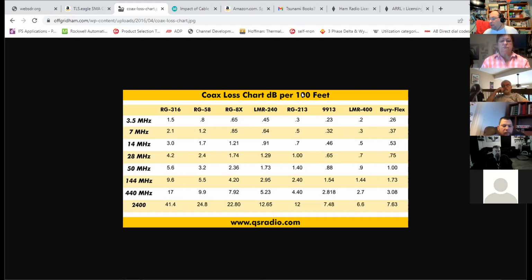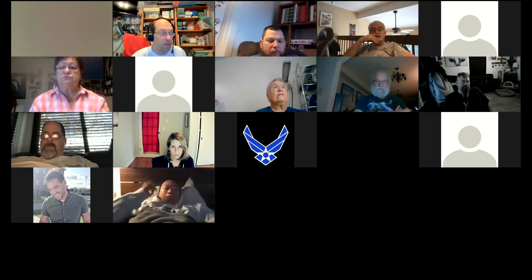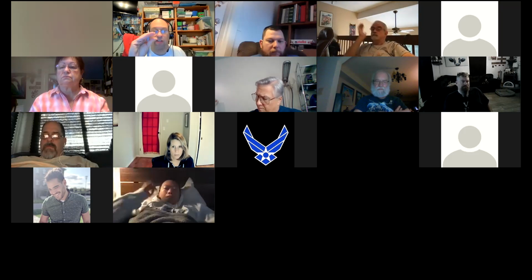So you have to look at everything based on how you're using it. And that's the tricky thing with cable. That's why it's important to know that those cable losses go up as frequency goes up, and the losses also go up as your dimensions go down. So the smaller it is and the higher the frequency, the bigger the loss.